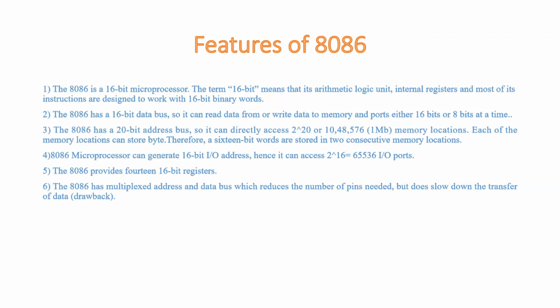But anyway, it will slow down the transfer of the data. And 8086 requires a single-phase clock. A clock is nothing but a signal which is used to provide a common internal timing for the synchronization of the operations of all the units available in 8086.